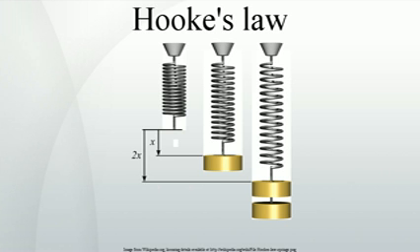Hooke's law for continuous media. The stresses and strains of the material inside a continuous elastic material, such as a block of rubber, the wall of a boiler, or a steel bar, are connected by a linear relationship that is mathematically similar to Hooke's spring law, and is often referred to by that name. However, the strain state in a solid medium around some point cannot be described by a single vector. The same parcel of material, no matter how small, can be compressed, stretched, and sheared at the same time, along different directions. Likewise, the stresses in that parcel can be at once pushing, pulling, and shearing.